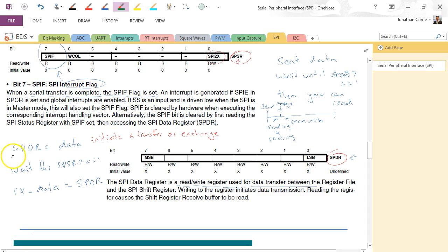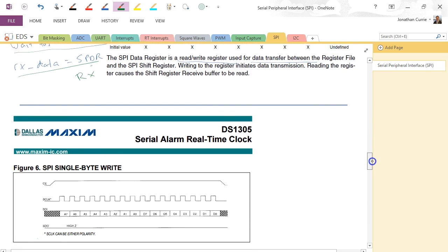So we see that this is transmitting and this is receiving, and it happens with the same register. That's quite critical. And remember, all we've received back is whatever the last set of data instruction was. If you haven't sent anything previously, then this will be rubbish. Right? And in order to receive back the information we're asking for in this data, we have to repeat this process again. But points to note, SPDR is for writing and reading, and it will contain the received byte after the communications has finished.